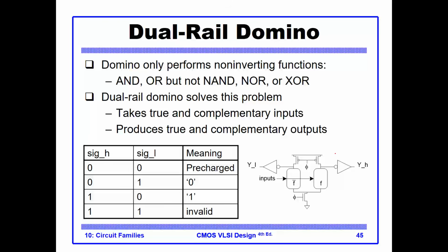In terms of domino circuits, people like to always produce the output of a function and its inverse, and there is a reason for that. Since we are forcing an inverter at the output of the dynamic gate, domino circuits tend to be true logic circuits, and there's a problem with that. What happens if you need to feed a negative logic or an inverted output to a dynamic circuit?